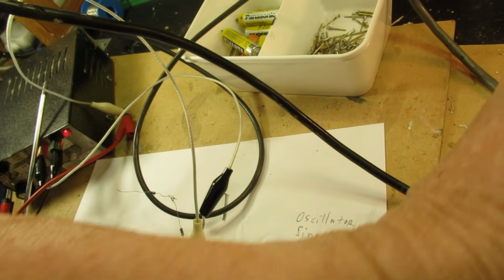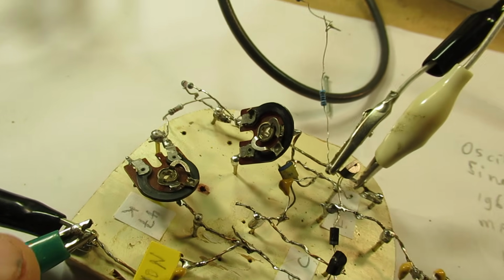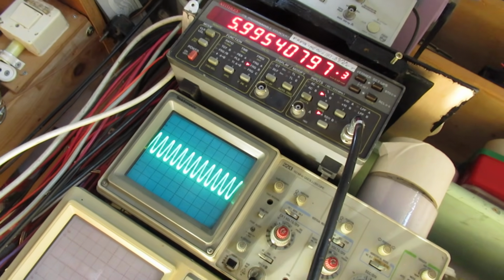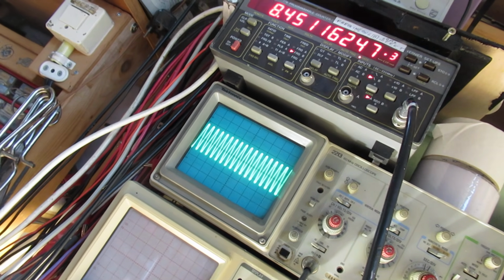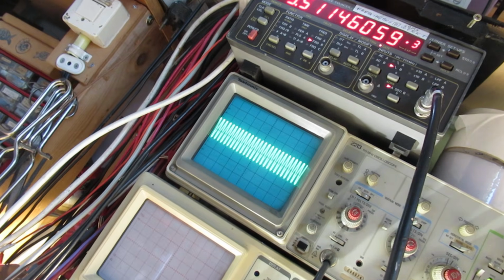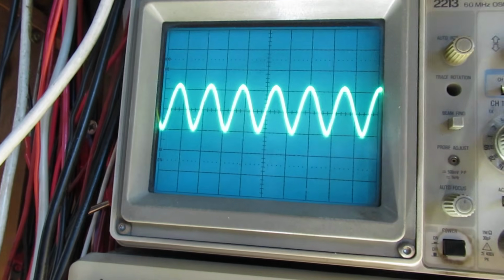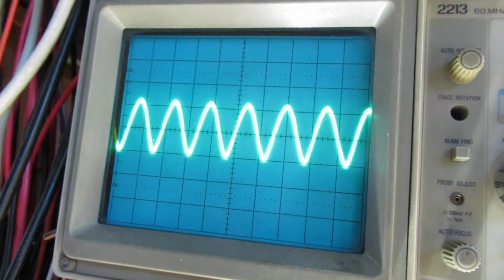Final thing to tell is the 2 potentiometers that bias the circuit. Both are 47 kilo ohms. So I turn them now with my hand. Let's listen and see. Now it's more or less inaudible, the sound, and it's surely inaudible now. 12 kilohertz, and I think, given the simplicity of the circuit, a quite good sine wave.